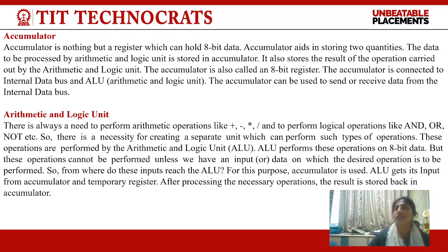So the first 8-bit data which is going to be processed by the ALU is first dumped in the accumulator, and the 8-bit result which is obtained is also stored back in the accumulator. The accumulator is also an 8-bit register. Accumulator is connected to the internal data bus and ALU. The accumulator can be used to send and receive data from the internal data bus.